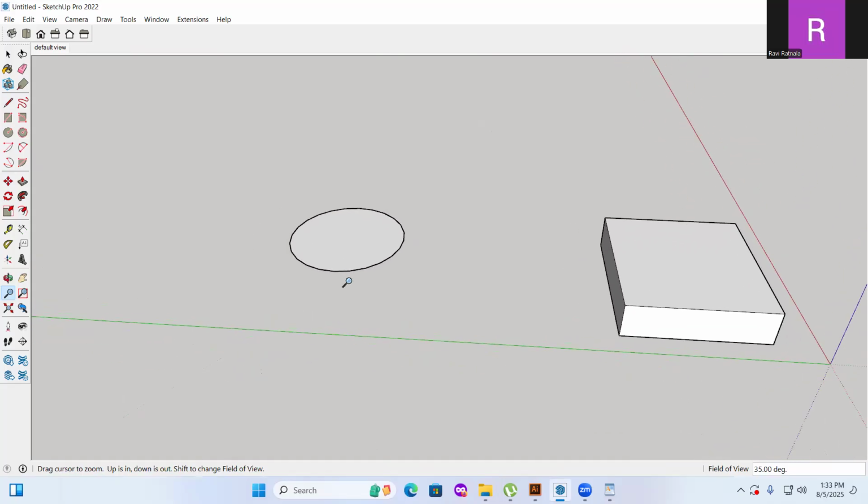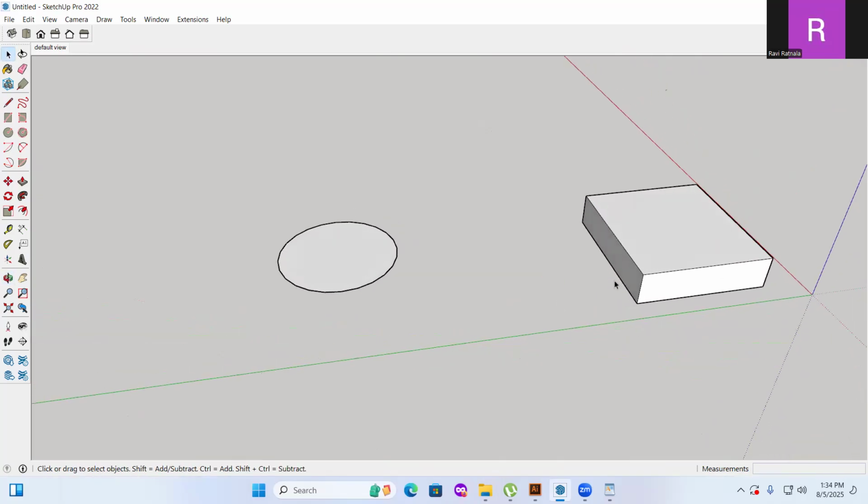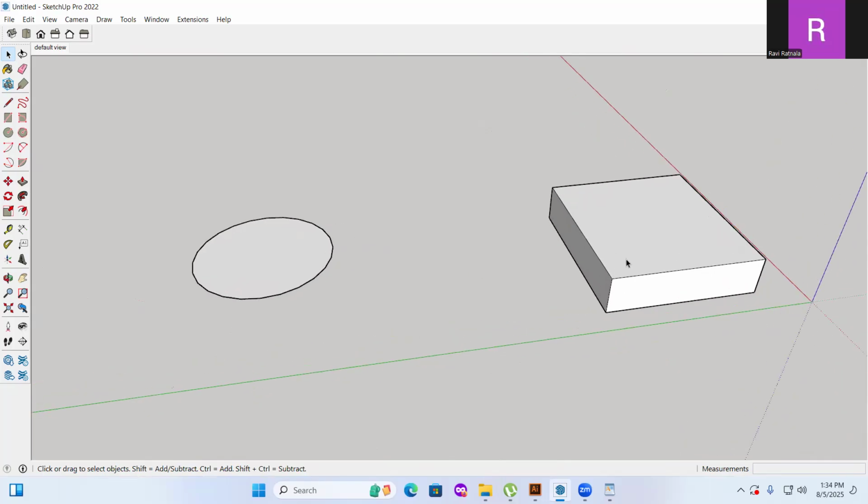Okay. And middle mouse button. The advantage with the middle mouse button is, in whichever tool you are, it toggles while you are holding the middle mouse button. When you release that, it goes to the previous tool. See this? I'm not completely switching, whereas O directly switches. I'm working with some tool, the selection tool. Suddenly I want to rotate it. Middle mouse button, rotate it, and again release that. Your previous selection tool is actually restored. So in more and more cases this will be important. Okay. So this is the thing.